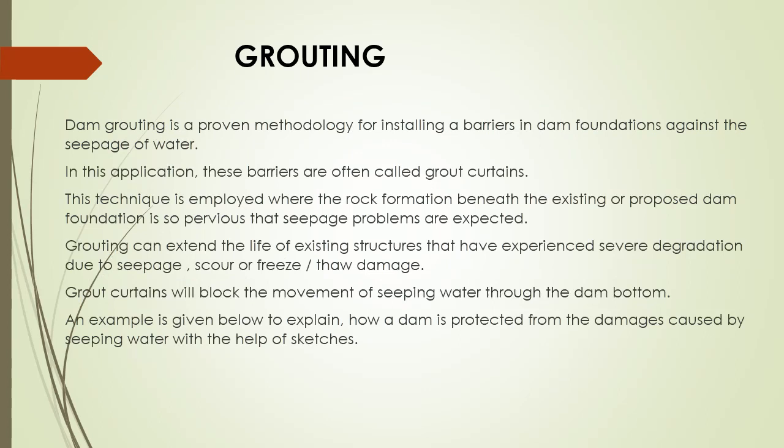Now we are going to another topic related to gravity dams. That is grouting. Dam grouting is a proven methodology for installing barriers in dam foundations against the seepage of water. In this application, these barriers are often called grout curtains. This technique is employed where the rock formation beneath the existing or proposed dam foundation is so pervious that seepage problems are expected. Grouting can extend the life of existing structures that have experienced severe degradation due to seepage, scour or freeze-thaw damage. Grout curtains will block the movement of seeping water through the dam bottom.